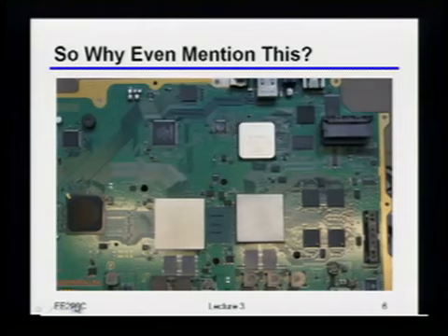Yeah? Board area is limited, so... Right, bingo. I've got a certain size board with a certain number of chips I want to pack onto that thing. And if I need, let's say, a terabit per second of throughput, well, if I can get twice as many single-ended links as I can differential links, hey, great. Then maybe I can actually get more net throughput per unit area, right?